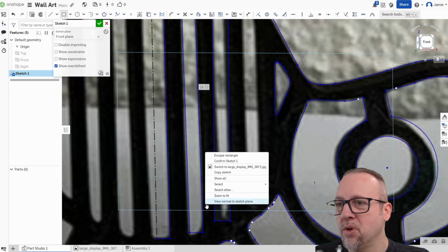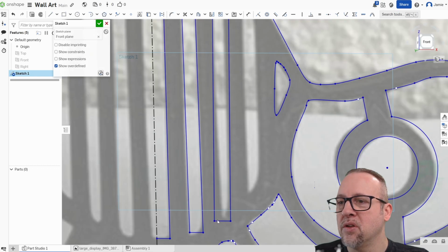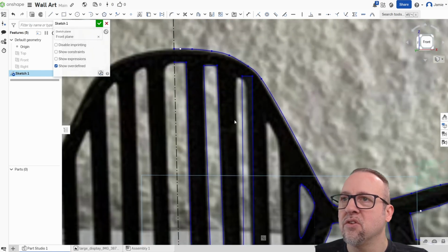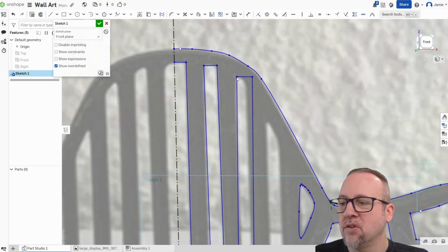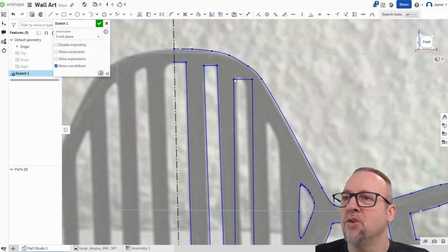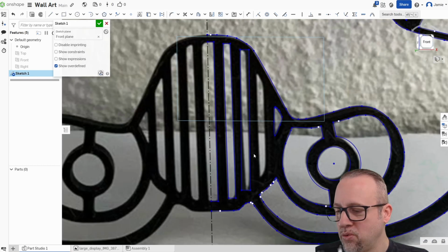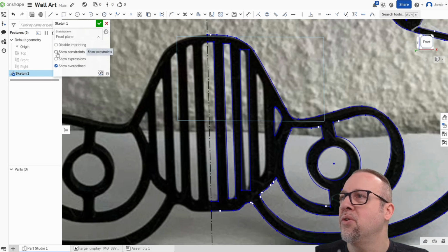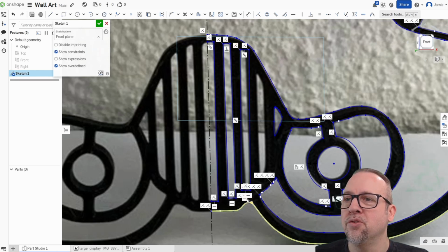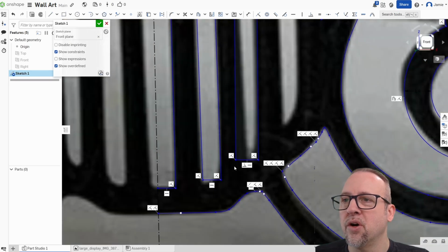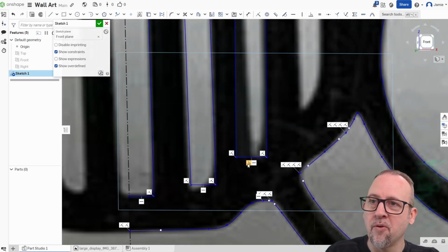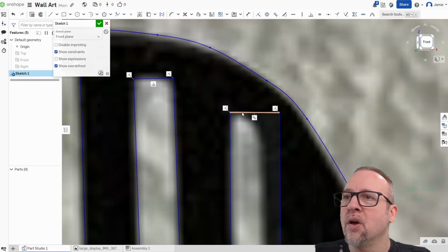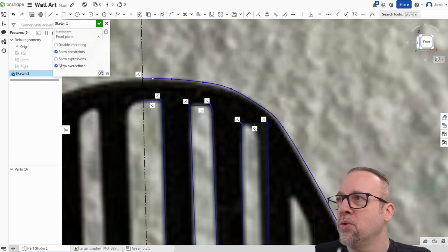So let's see what happens when I escape the rectangle and then I grab that one edge. So let me hit my shift key, see what I can do. No, that doesn't do anything. All right, so I see that perpendicular. I don't like perpendicular. I don't want that perpendicular. So where is that perpendicularity callout? There it is right here. So we can delete that guy. Okay, now we just have some coincidences. No perpendiculars up here, so that's cool.